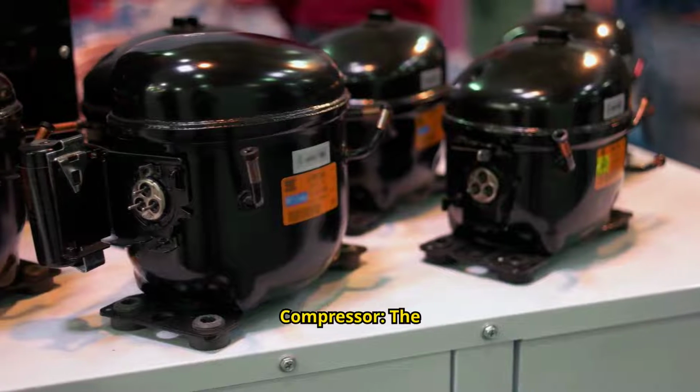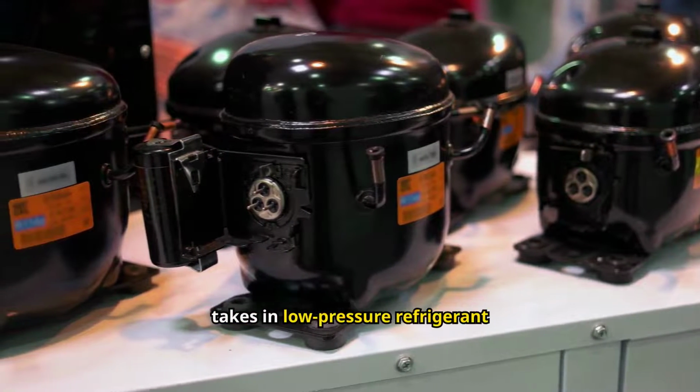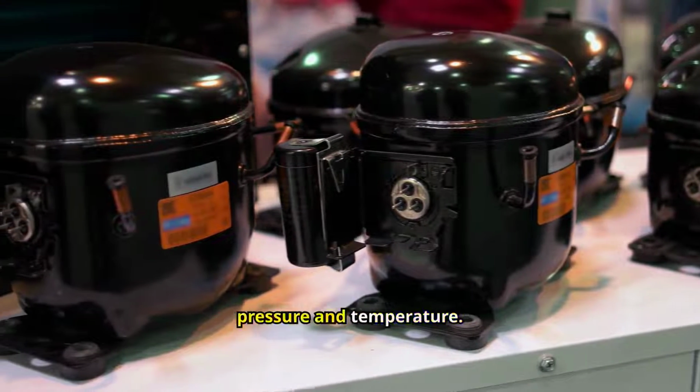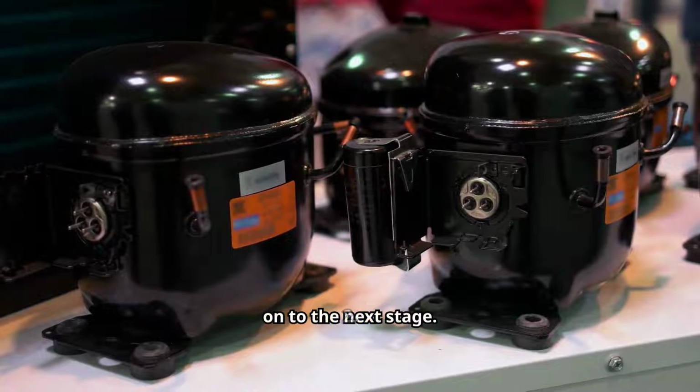1. Compressor. The compressor is the heart of the refrigeration system. It takes in low-pressure refrigerant gas from the evaporator and compresses it, increasing both its pressure and temperature. This high-pressure gas then moves on to the next stage.